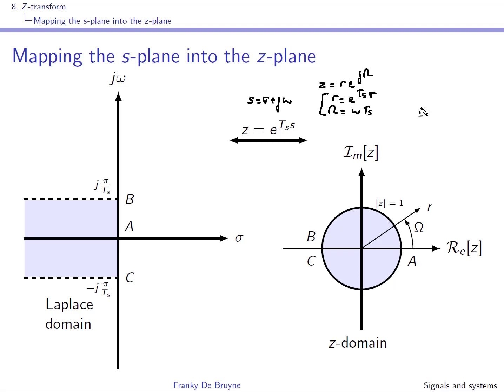So what we'll do is select this discrete frequency in the interval minus pi to pi, and we'll consider in general that r is positive or 0. If we have a look at the corresponding analog frequencies, we have to divide by Ts, so we see that omega, the analog frequency, is in between minus pi over Ts and pi over Ts, right?